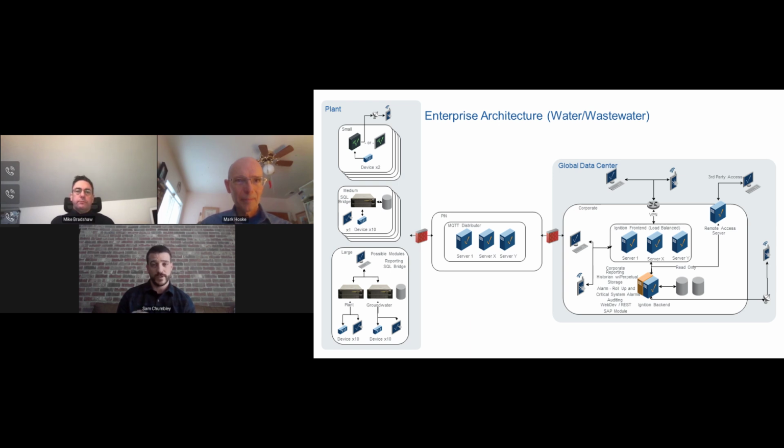So it's 3 redundant pairs of Ignition SCADA for HMI, Ignition Historian, which is a SQL node, so redundant SQL, redundant SCADA, and then finally redundant Thin Manager for some of those sites that have multiple clients and managing those clients. So moving from left to right, we've got what American Water refers to as the PIN network.